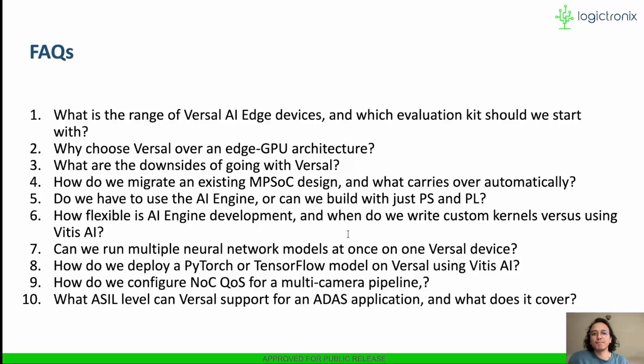So this means we can build a full ASIL D path for fusion, control and vehicle communication from the sensor fusion core through the NoC to the CAN output without the need of an external microcontroller. Since the inference itself runs on the AI engine, which is targeted for up to ASIL B, if our safety case needs perception output that is certified for ASIL D, then that requires a careful safety case study and might need some redesigning also.